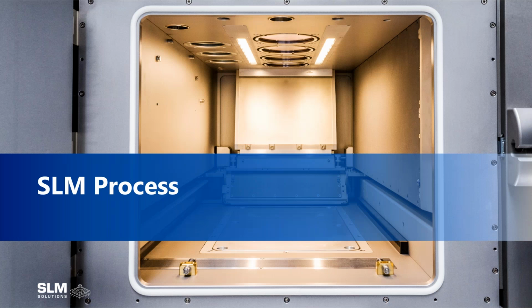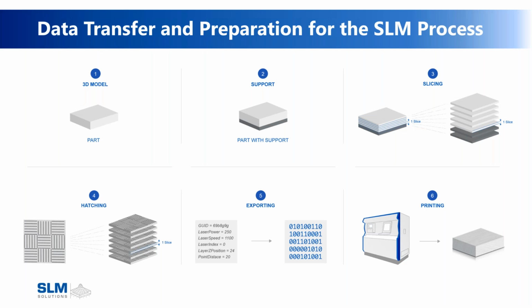And a little bit more about that process. So we start with a model. Typically we use an STL model, a wrapped triangular model. That model is then supported. So an additively manufactured part, which has design considerations for build orientation, might not need support, but a more traditional part may need support material added to it. That material is the same material as what's being built inside the system. It is not a secondary or a dissolvable material.